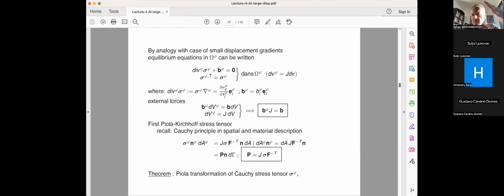And if I go from large displacement to small displacement, I simply remove the phi, it becomes identity, so no need to write it. And I get back my equivalent equation that I had in a small deformation setting. So basically, for that case, it's rather simple. I can solve the problem because the only unknowns are stresses, and it's in the category of statically determinate problems where stress is obtained directly from, let's say, equilibrium equations and whatnot.